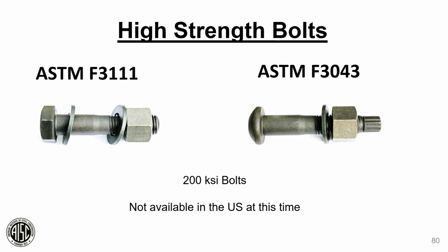But there are some limitations on the use of these bolts, even if you wanted to use them. They can only be used in non-corrosive environments. So they can't be used in conditions where they would be wet all the time, because they will corrode. So there are a lot of limitations with the use of these bolts, and they are not available in the United States. We hope they will become available again soon, but they presently are not available.